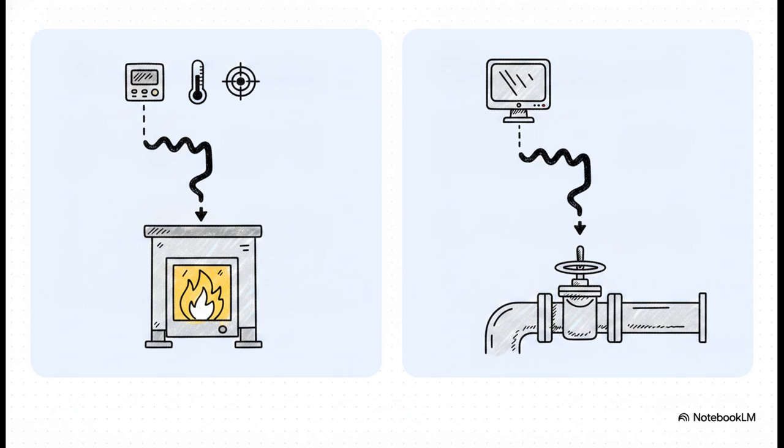Think about it. The current room temperature that you're feeling right now, that's your PV. That super comfortable 72 degrees you punch into the dial, that's your SP. The electronic signal getting sent down to your basement, that's the OP. And the gas valve physically opening up inside your furnace, that's the MV. It perfectly translates our four industrial terms right into everyday comfort.